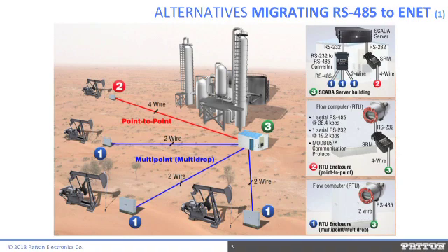From this central location, the operator can calibrate, program, or configure the flow meter, request a data dump, or execute other operations. The flow computers in the application diagram have either an RS-232 or RS-485 electrical interface that operates at a maximum data rate of 19.2 or 38.4 kilobits per second. The SCADA server uses RS-232 interfaces that connect to modems, making links to the derricks.